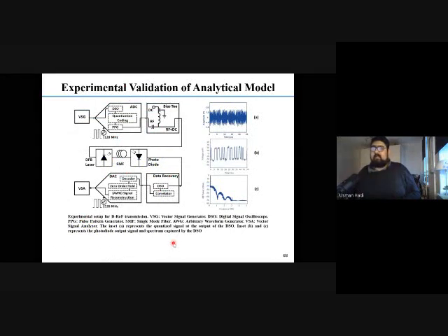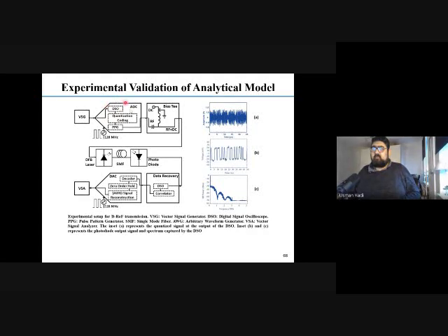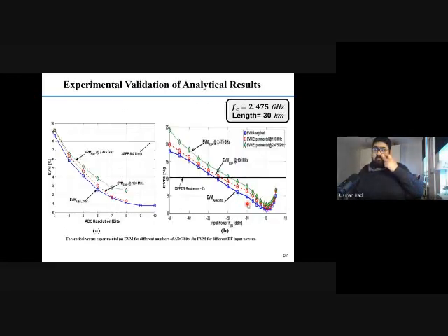Just to give you an idea, this is the way we model it. When we have the quantization, when we have the ADC, it means we have the digital signal oscilloscope, we have the quantization, we have the pulse spectral generation, we have this undersampling at 128 megahertz, the biasing, the fiber, laser, photodiode. Then we have again the correlations, the DAC, where we have the zero order hold, signal reconstruction, and then the signal analyzer. And then you can see the amplitude, voltages, and RF powers that we have at 2.4 and 3 gigahertz. This is how we validate this system.